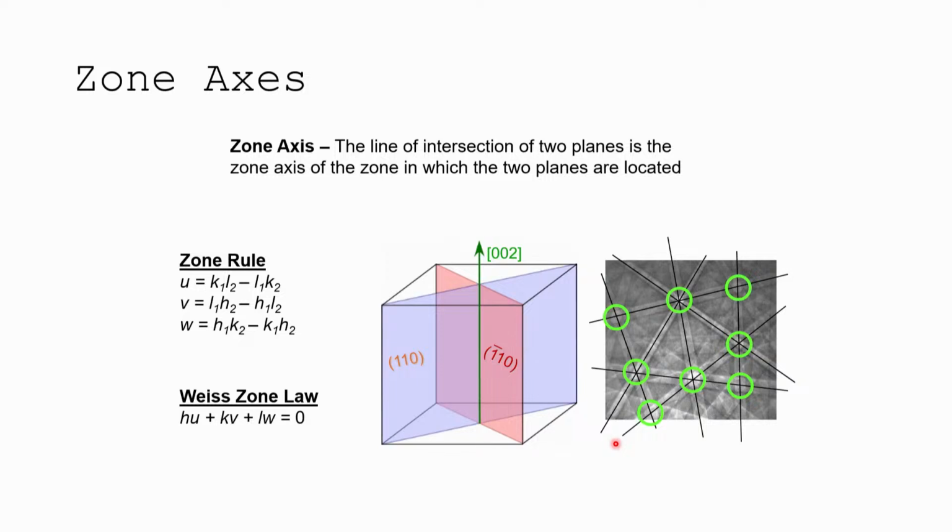Just the way TEM diffraction works, because of how high the energy is, the electron beam is effectively aligned up in the plane of the diffracting plane, and then you get spots coming off of that plane. So we always define a TEM pattern by the zone axis that we're looking at. Right? And really what that means is we have these planes that are diffracting, and that zone axis is shared by those various planes.